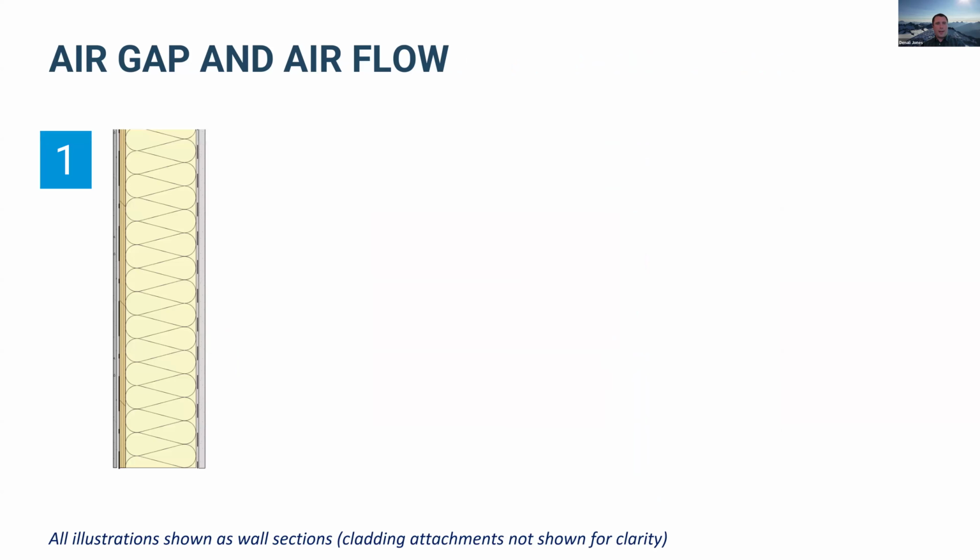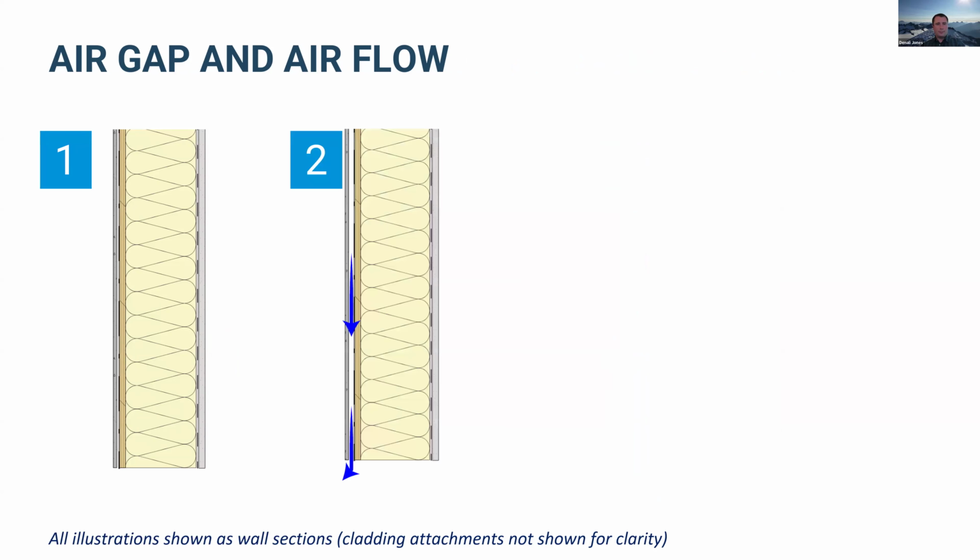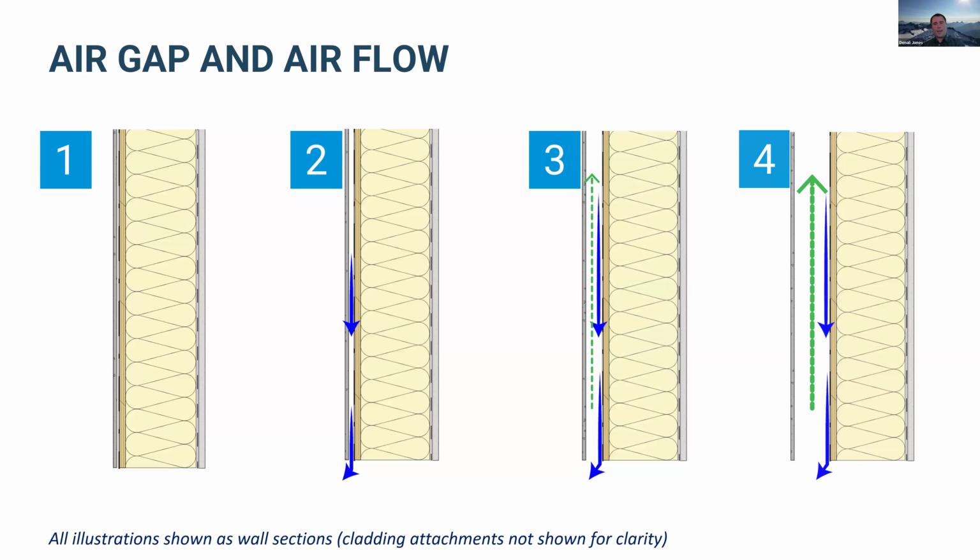All right, so let's talk about gaps. So how big does the gap need to be? Really not very big. There have been lots of studies on this. We don't actually need much of a gap at all to allow drainage. We do need a bigger gap to allow any kind of decent drying potential in terms of airflow. But there have been lots of tests done that show that a gap as small as even a 16th to an eighth of an inch will allow for some drainage, so liquid water could drain out of it.